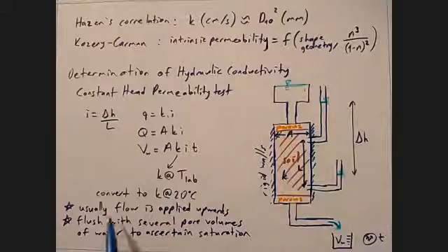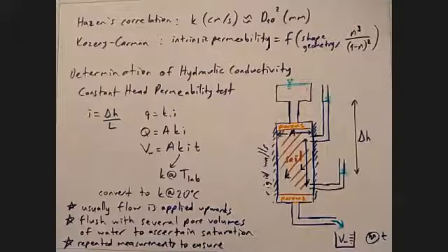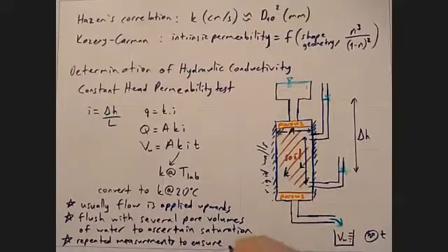That's why I said usually flow is applied upwards, because that's the process to saturate it. And then repeated measurements to ensure steady state and also laminar flow.